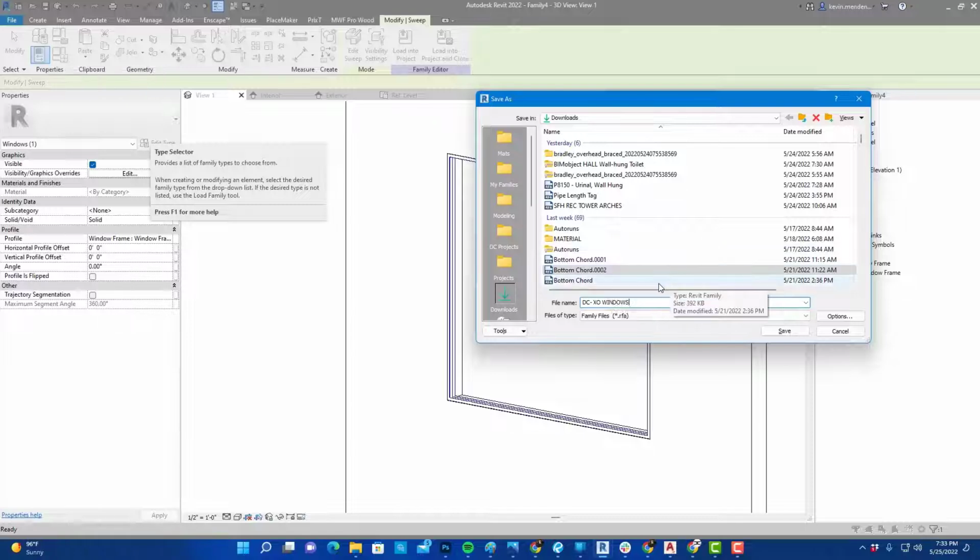But a quick note, I don't typically save all the parts to my families. I do save them, but I save them as temporary. So I'll throw them into my downloads folder. I import those into the final family, and that's where they're stored. I don't keep all the parts and pieces.